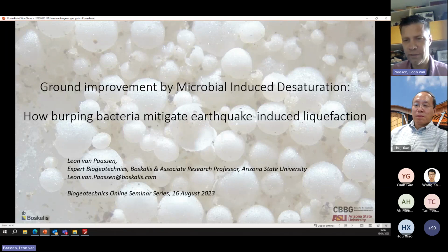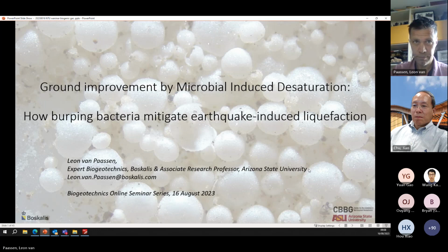Okay, perfect. Today I want to talk about one of the processes I've been working on, mostly at Arizona State University, but also already in Delft and still a little bit at Boskalis. It's about ground improvement using microbially induced desaturation. In other words, how we can use burping bacteria to mitigate earthquake-induced liquefaction. In the background, you see a result of this process, which are calcified gas bubbles. I will show you in this talk how we can try to use that